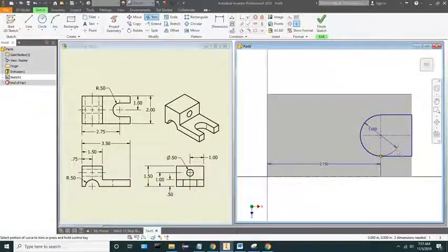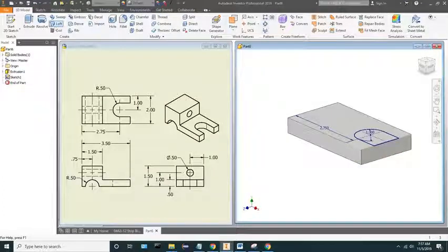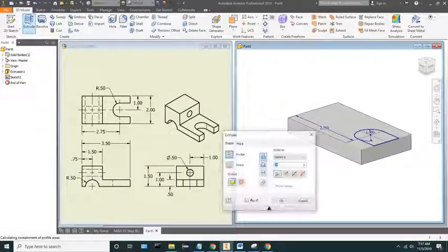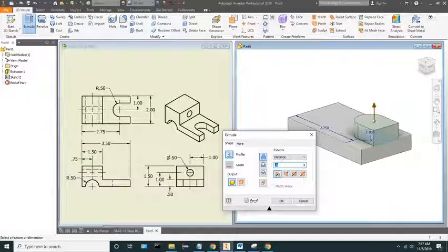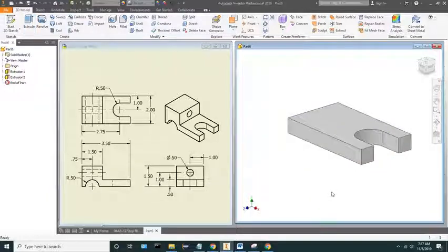This arc here is just a dimension line. So this completes my enclosed shape. I can click Finish Sketch, and I have my enclosed shape that I can extrude. So I'll select Extrude, but then I want to cut extrude this. So in the Extrude box, I'm going to select cut, and I do want to cut 0.5, half an inch. Click OK, and that completes the notch.